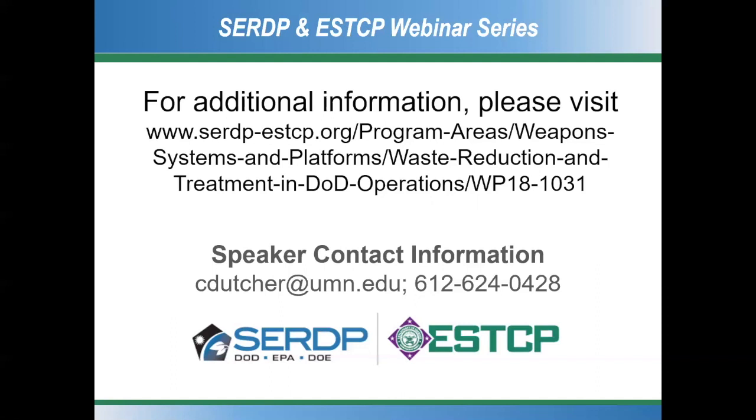Great, thank you, Carrie. Another question for you. What are the limits to your measurements? For example, what governs the lowest droplet sizes detectable in your turbidity measurements? Yeah, turbidity in general is not a perfect measure. It depends on how much light gets scattered, because a lot of things will influence the way light interacts with particles. Certainly the number of particles will influence it, and that's what we're trying to get at, the concentration. But the size of the particle will also impact that.